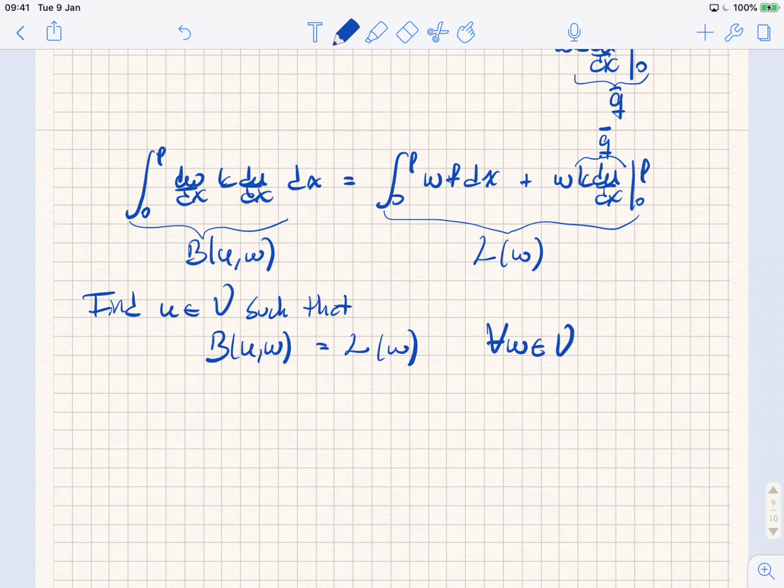We said, well, I want that space to basically already be zero at all the parts of the boundary which have Dirichlet boundary conditions, because we really want to remove that reaction force in the case of elastostatics. In this case, you can call it reactive flux. Okay, reactive flux it is. So that V, remember, was defined as a set of functions v such that v evaluated at the portion of the domain gamma u is equal to 0, or the restriction of v in gamma u is equal to 0. Okay, so that's it.